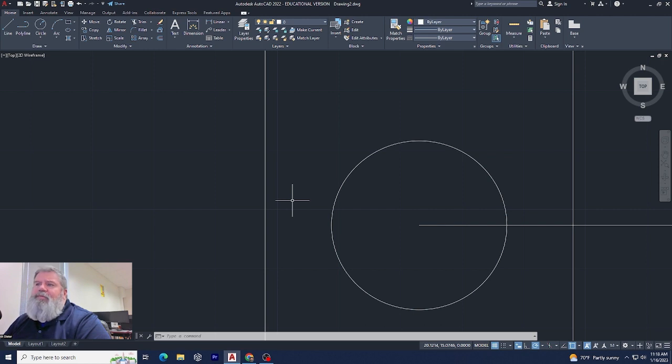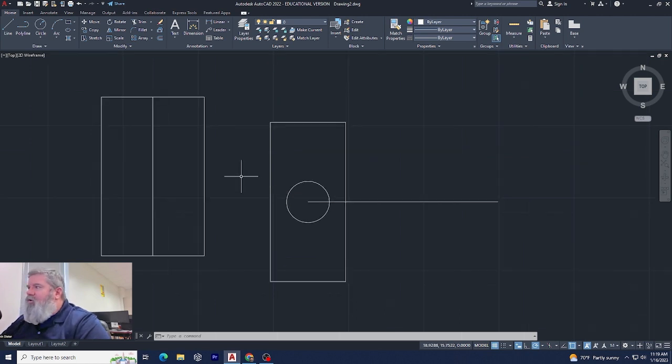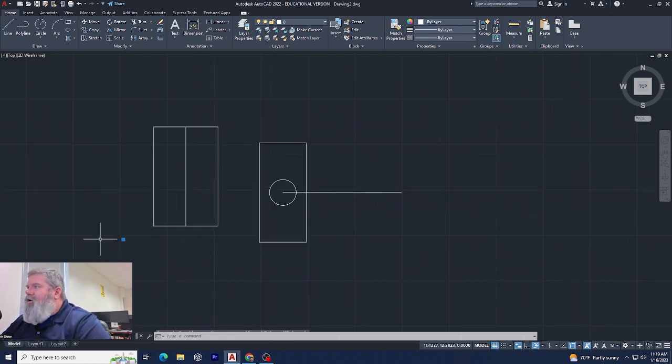Now, with any of these methods, object snap modes are active only for the selection of a single point. When you're using single point snap, if you want to object snap to another point, you must select an object snap mode again for the second point. But if you just leave them on, your object snaps will run. That's how I did it all the time when I worked in industry. My object snaps were always on, especially the ones I used all the time, and I only turned on specific ones like tangent or parallel when I needed them, not constantly, okay?